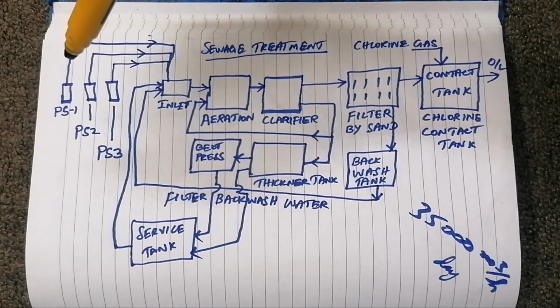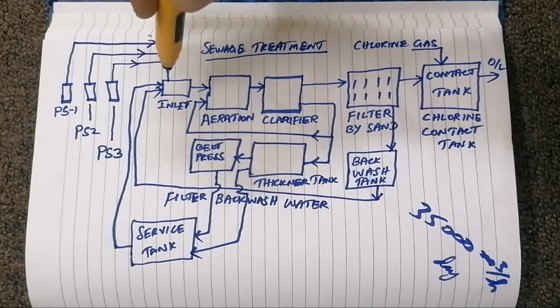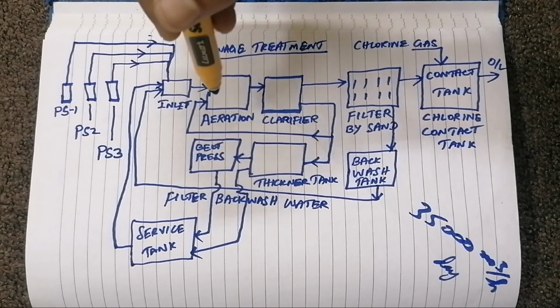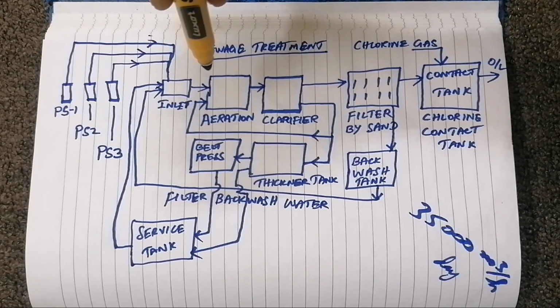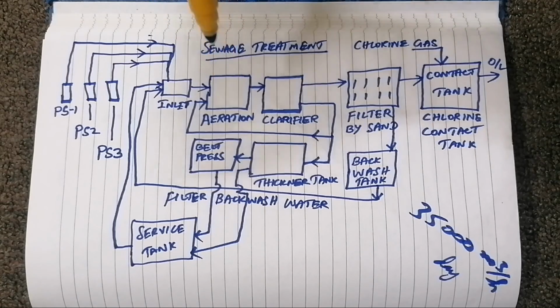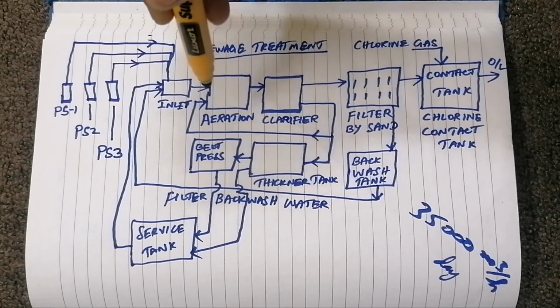The water coming from the customer side, from the domestic usage side, has a lot of toxic microorganisms and a lot of toxic gases. With different pH values, the water will be more toxic, especially ammonia. Ammonia is a very toxic content in the water. So what we have to do is remove the toxic content from the water, and for that we need the aeration tank. The aeration tank gives air to the water which contains ammonia.